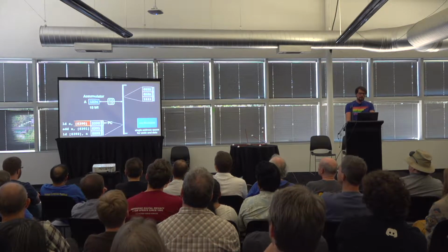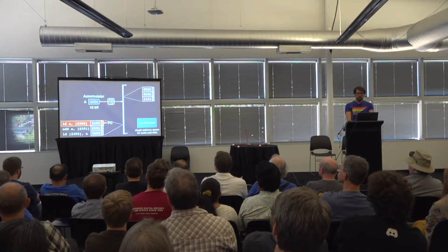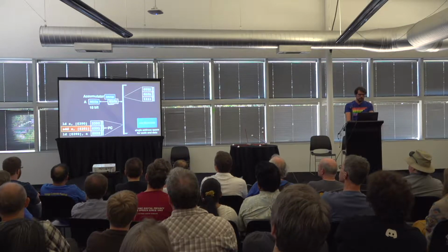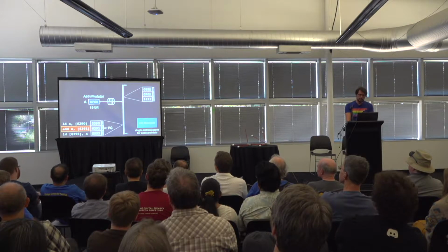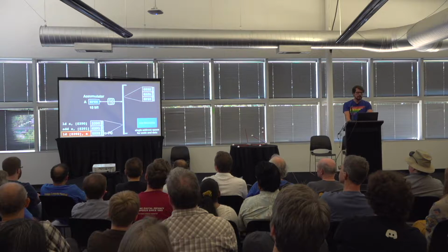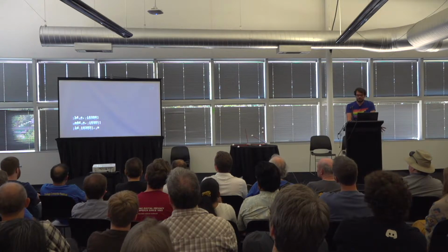The CPU's program counter, PC, always holds the address of the instruction to be executed next. The load instruction copies the contents of a given memory cell into the accumulator. Then the PC goes to the next instruction. The add instruction adds the contents of a given memory cell to the accumulator. And the store instruction copies the value in the accumulator into memory at a given location.